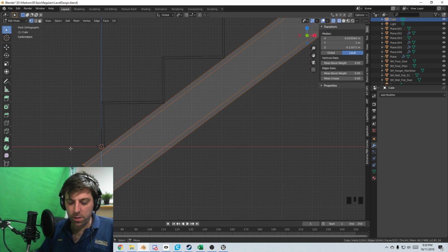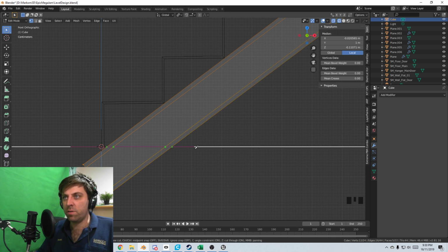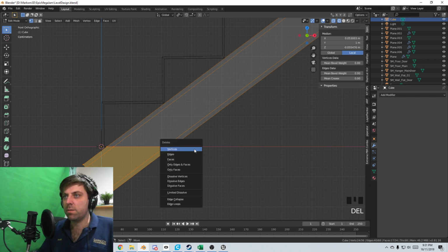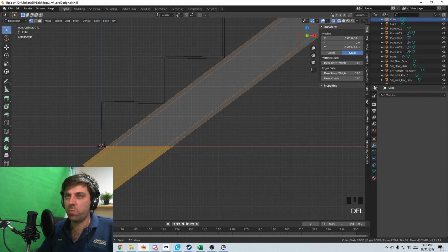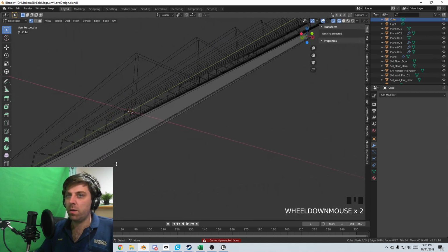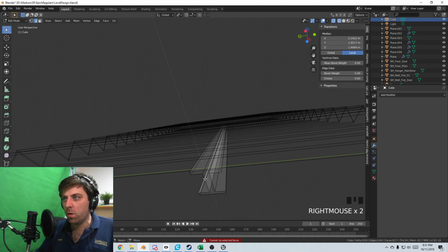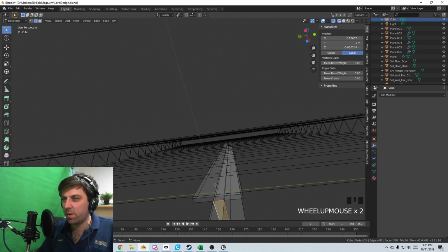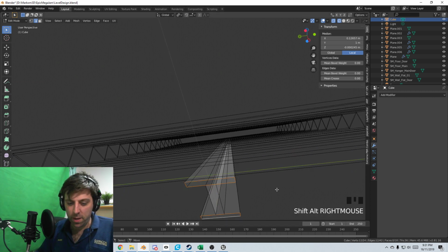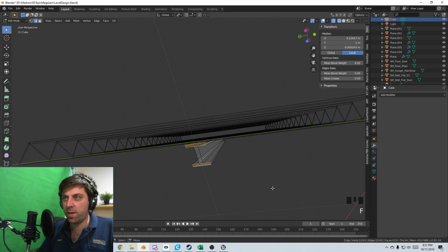And then I'm going to be super lazy. K for knife tool, Z so it cuts through everything, C so it goes on 0, enter, delete. Actually, we'll go V, delete faces. And there we go, we've now quickly made an I-beam. Wham bam, thank you ma'am. And that's flush with the floor now. Face.